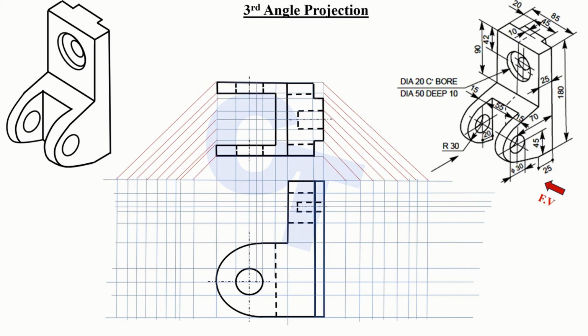So this is what we have right here. And now what we're going to do, we're going to start by drawing the right view, right? Okay, so on the right view, you can see those are the planes that we have, right? But if we look right here, I'm going to see this one is flat, right? And also this one is flat, right? And we have some hidden details. So let's draw. First, we're going to name our planes. So it's plane number 2, and that one is going to be plane number 1.